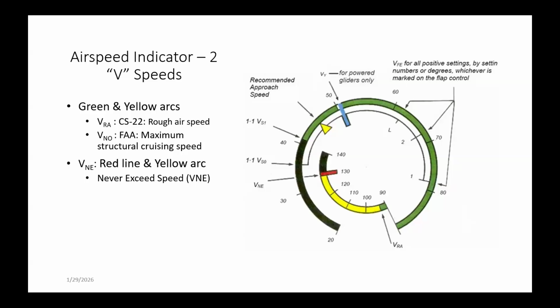The maneuvering airspeed, the one that we call VA in the United States, it's generally below the VNO or the VRA. It ties to accelerations that can be induced with control inputs. It depends on the mass of the aircraft. The lighter the aircraft, the lower the maneuvering speed because you can get it moving. You don't have the inertia of the additional weight dampening it.